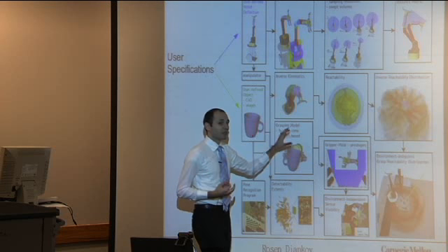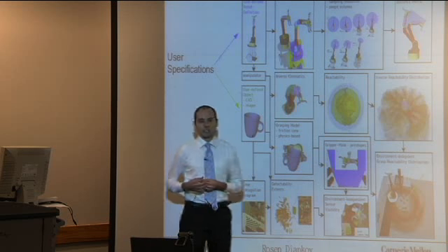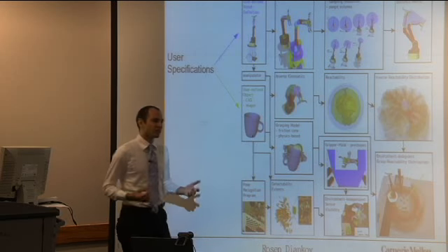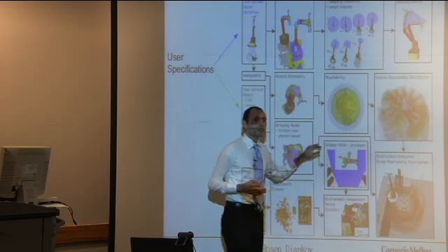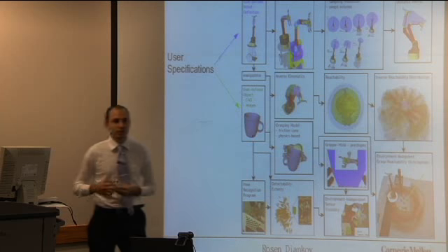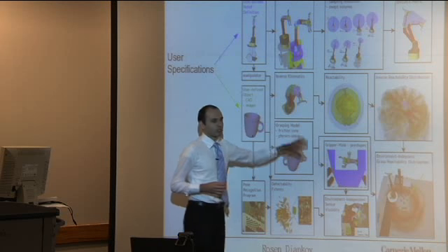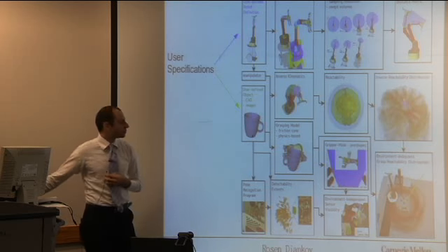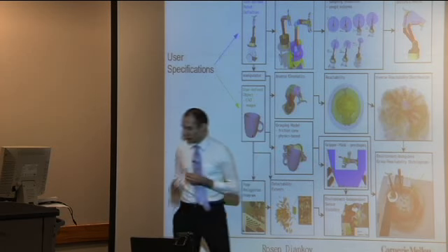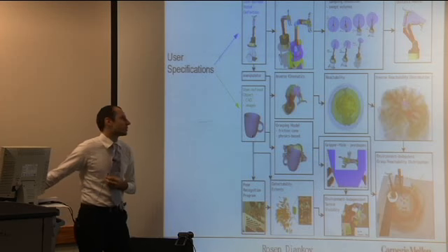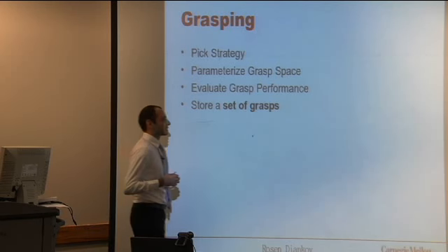the inverse kinematics, the reachability, very geometry-heavy analyses that are commonly used in planners, but require a lot of computation to cache. By developing this type of computational dependency graph, we can easily track how information gets processed throughout the system, and whenever something changes in the tasks, we can know exactly which component to regenerate. So I'm going to begin talking about these one by one and guide everyone through where the contributions in the thesis are. So the first is grasping, which is, in some sense, the most important for